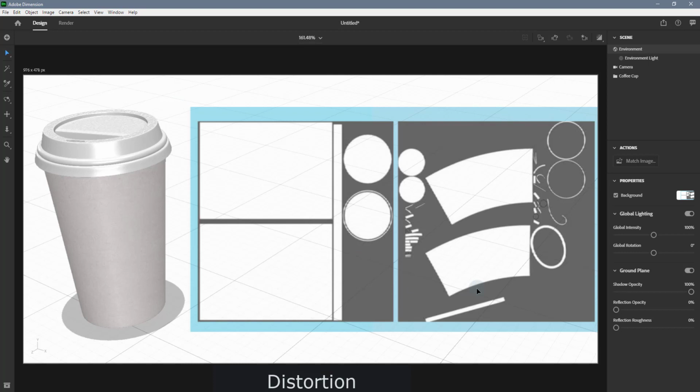Distortion. UVs can be squashed and stretched. Usually the artists and UV unwrapping algorithms attempt to minimize distortion, but it's sometimes impossible to have UVs be completely distortion-free. You can sometimes distort the graphic in the UV image to counter the distortion in how it's applied to the model. Seams. When UVs are created, the model is broken into areas, called UV shells.